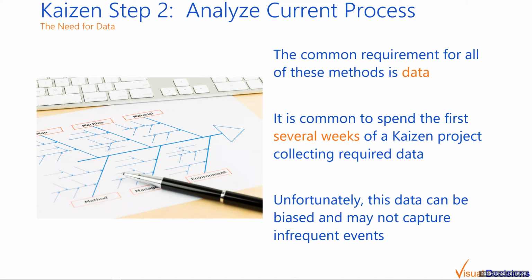For those, you can very easily tie in, for instance, an OEE system that collects the amount of downtime, as well as what the individual causes for the downtime were. Now, this fishbone diagram can become a Pareto of the different factors that are driving downtime for that machine. And if we're collecting that information 24/7, if it's always on from a data collection point of view, when we start that Kaizen event, we'll have that information.